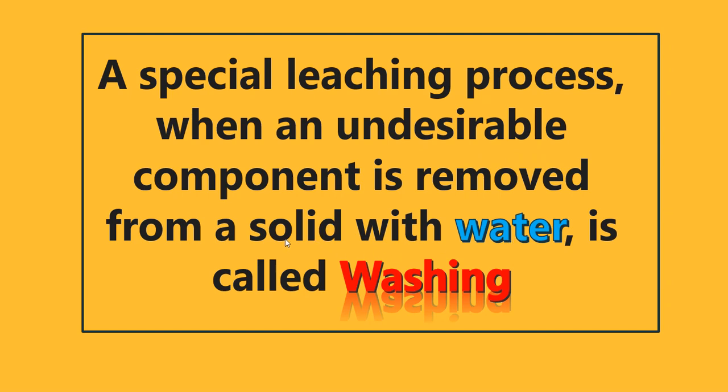That particular solid that we dissolve using our solvent water is of course processed by the special term used in leaching. Actually, this is still leaching but only referring to leaching which uses water as the solvent, and that particular term is washing. So we simply wash off the undesirables or the other inert solids that are present in our solid matrix, and we want only to recover that constituent or that solute from that given solid matrix. If water is used as the solvent, then the process is simply referred to as washing.